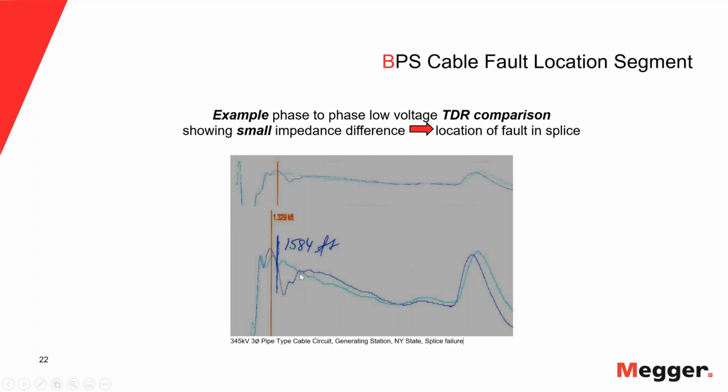And we were lucky, it did thump, and it was right in the splice, the first splice in the manhole. So I'm just saying, the indication to find that spot was through the phase comparison method. It's a very powerful tool when you have multi-conductor cables or multi-conductor circuits.